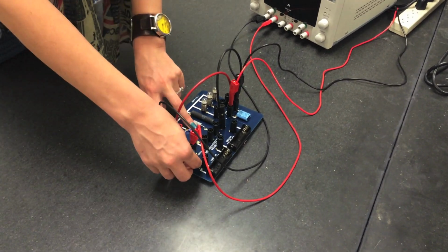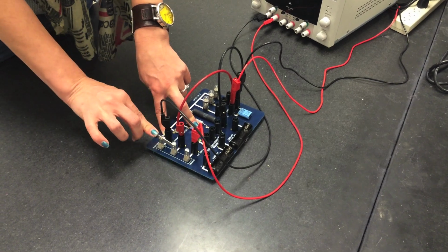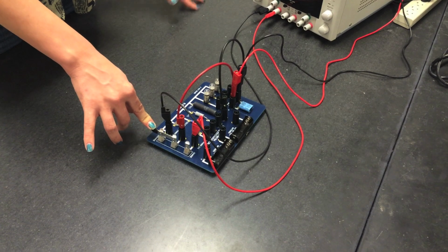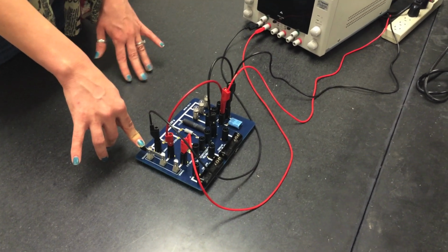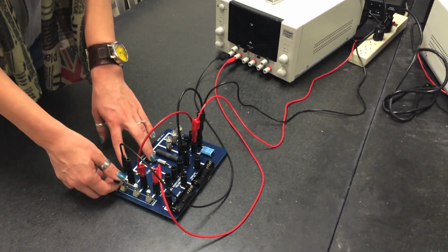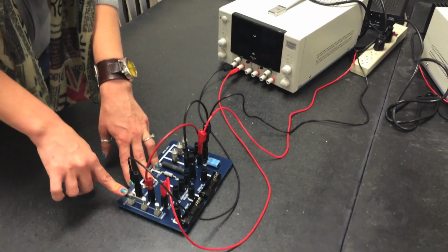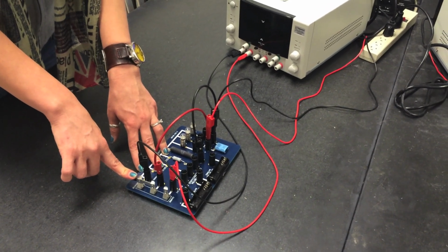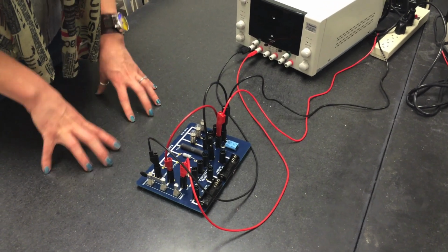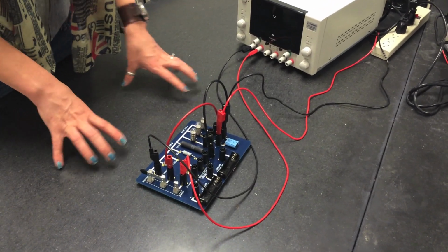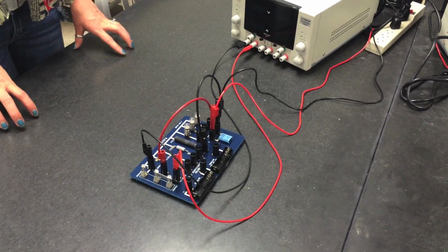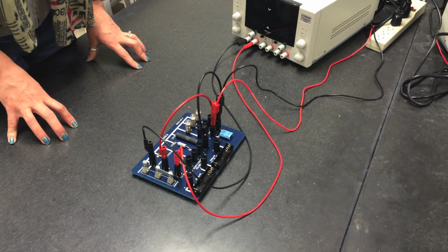If, when you are at the discharge position, the potential on Data Studio doesn't initially show 0, that means the capacitor was not properly discharged from the previous class. Return this switch to the discharge position and wait until the potential is shown to be 0. After that, you can start collecting the data following the steps. Press start, wait 5 to 10 seconds, and then move this switch to charge, and now you're going to wait for 200 seconds for the capacitor to fully charge.